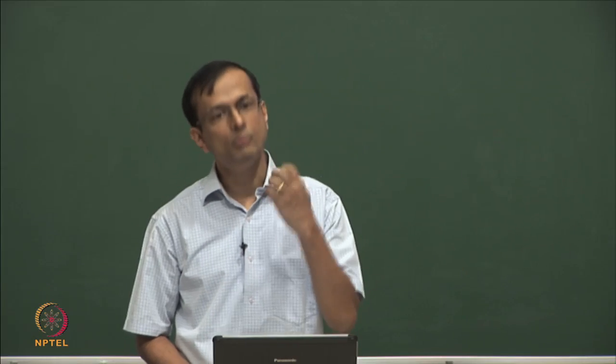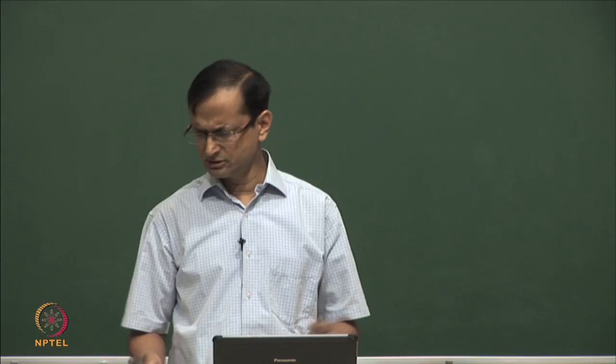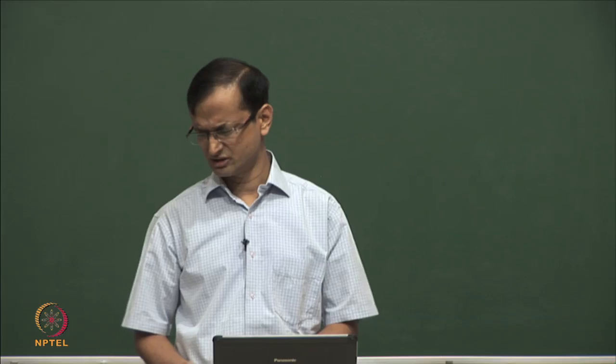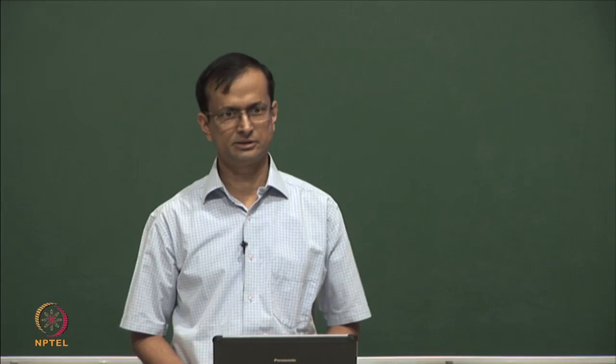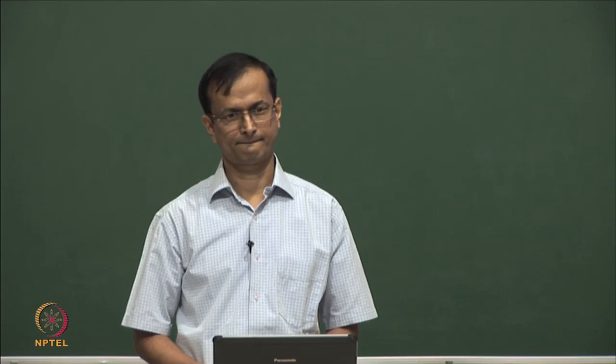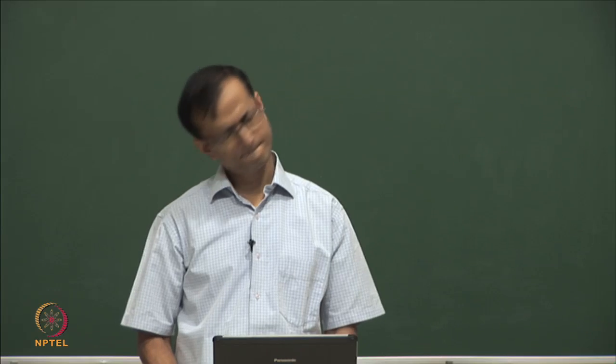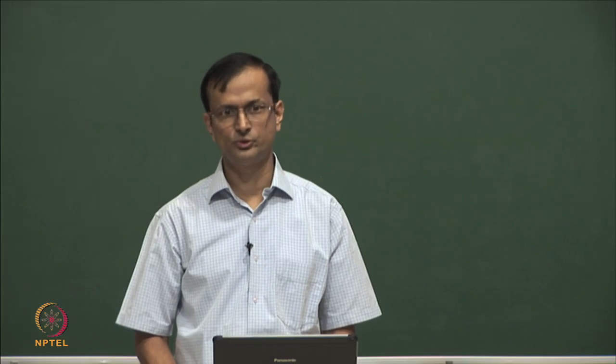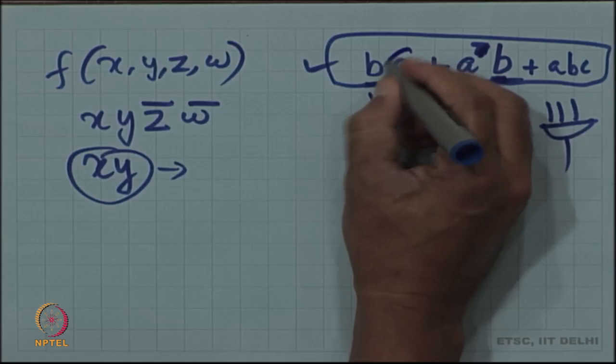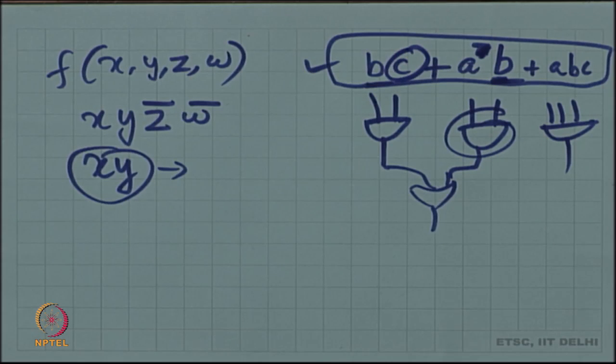That's why it translates to more area, and the equivalence here is that it is like a 2 input gate or something like that. Basically, that way you are able to cover the logic implementation details also in one shot. That is what we are trying to estimate. Every time something like this occurs here, it translates to 2 transistors in the logic implementation.